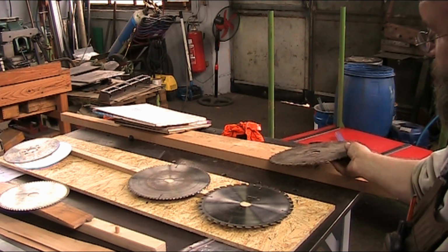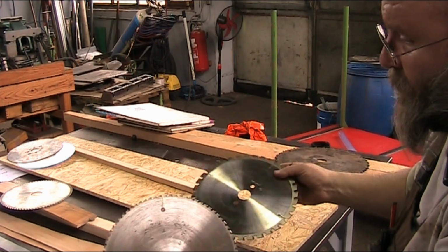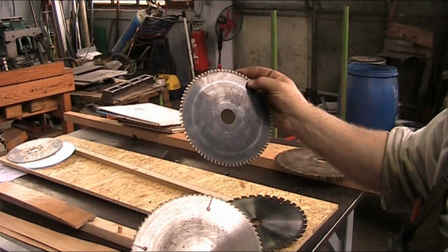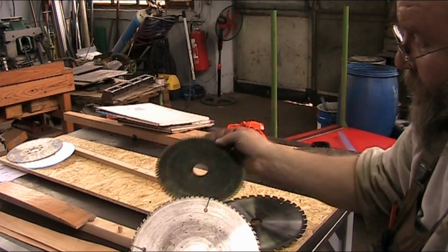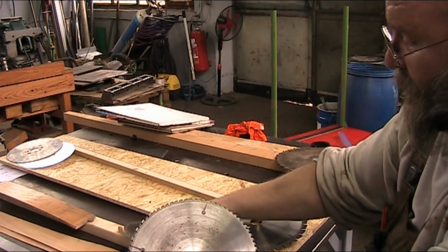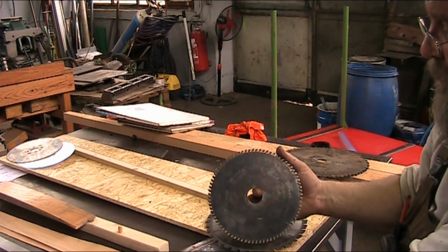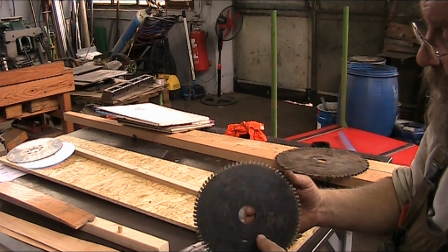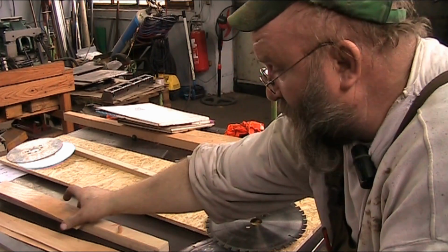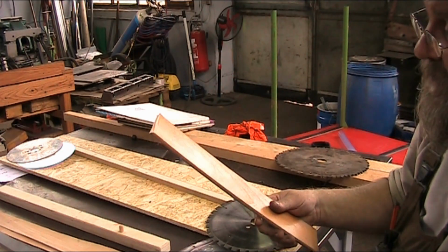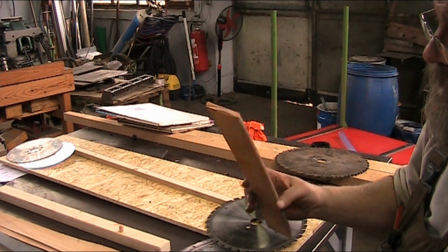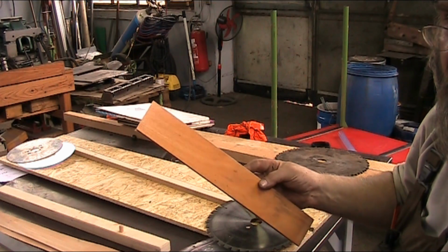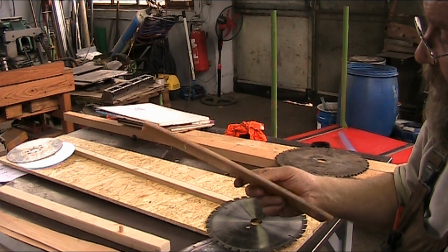Now here we have some carbide tip blades, and these all have different functions. Now, as I mentioned before, the finer or the harder your material is, the finer the tooth you're going to have to have. Now in plywoods, you have hardwood plywoods like this. This is out of a bed frame, actually like a box spring. The Europeans like to make these things, and this is out of beechwood.